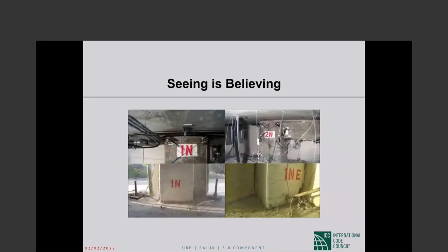We don't even call them dual systems. We simply call them shear wall frame interactive systems, and we design them on the basis of interactive analysis. There is no 25% backup frame. That is the short answer to your question. This dual system concept doesn't apply unless there is inelasticity in the picture.